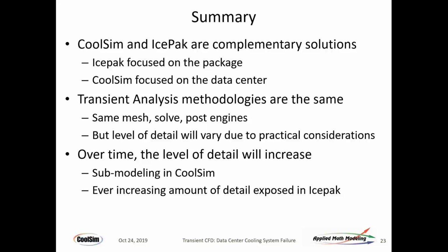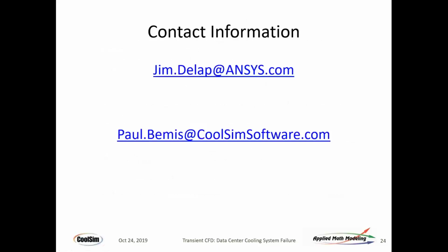When I talk about practical considerations here, I'm talking about compute time and the amount of data. The compute time, remember, for a mesh that is 10 or 20 million cells is going to be a few hours, and that's when running it in parallel on a cluster like we do with CoolSim. So you have to be practical with respect to your expectations about what can be done. Having said that, over time, the fidelity has been increasing and simply going up. So you can expect more of it tomorrow than, in fact, you saw today. So with that, I'm going to open it up for questions.